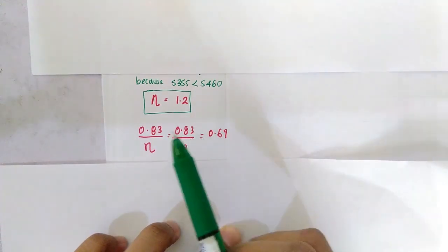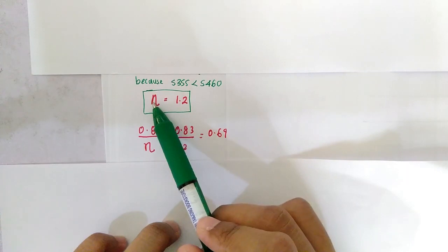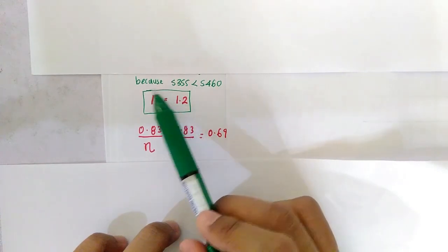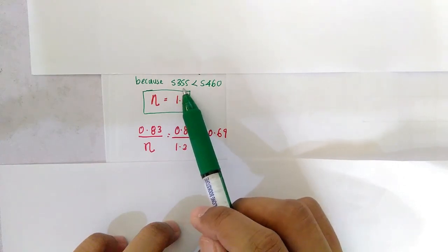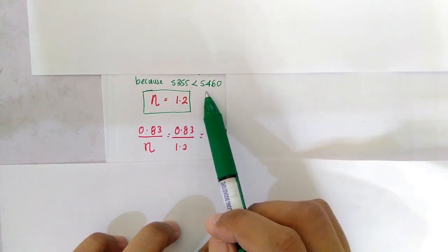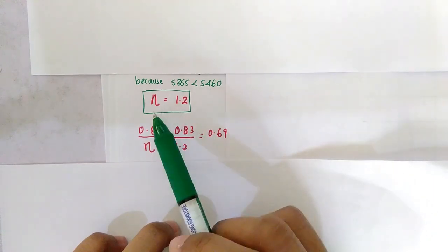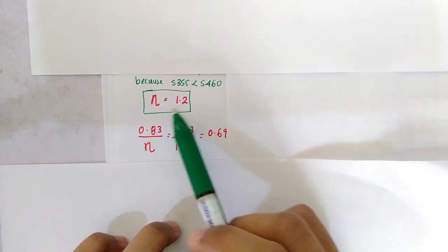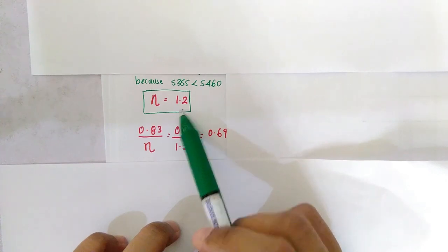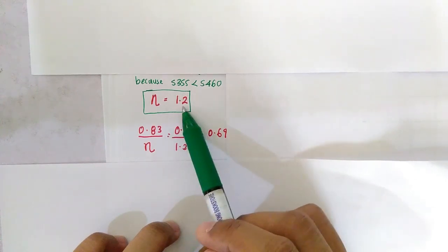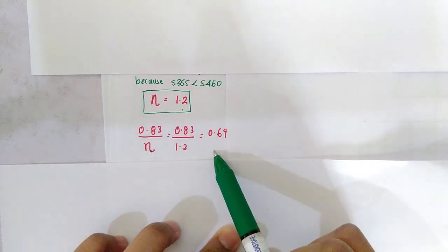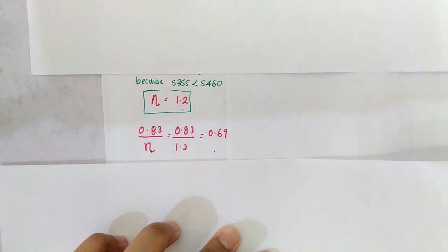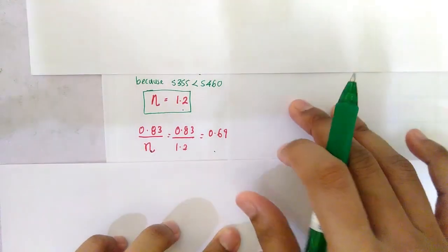So in this particular case, what is the value of this parameter? Recall that in this case, your grade of plate girder is S355, which is lesser than S460. Because of that, your parameter eta is equivalent to 1.2. Substitute the value 1.2 in the equation given in table 5.1, which gives you 0.69.